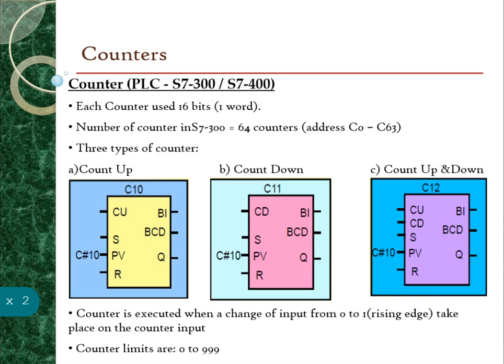In order for you to keep track of these 15 boxes, you need a counter to count the boxes. There are 3 types of counter that are used in PLC programming: count up, count down, and count up and down, which is a combination of up and down. In order to differentiate the types of counter, we just need to differentiate the value of an input, which is the direction of the counter, either up or down. Later you are going to see it clearly in our demo.